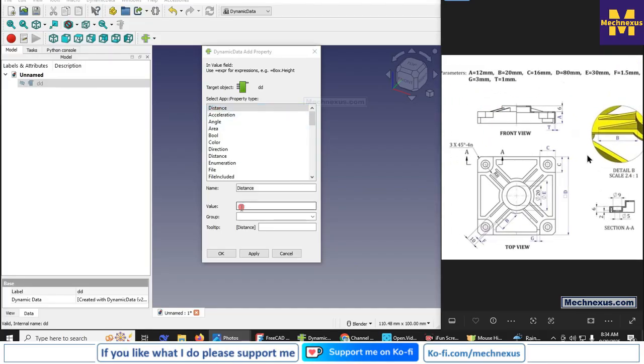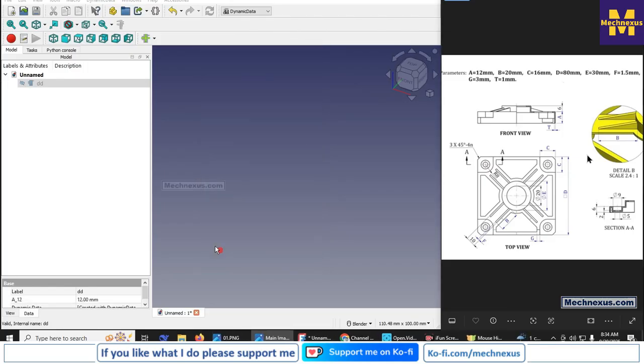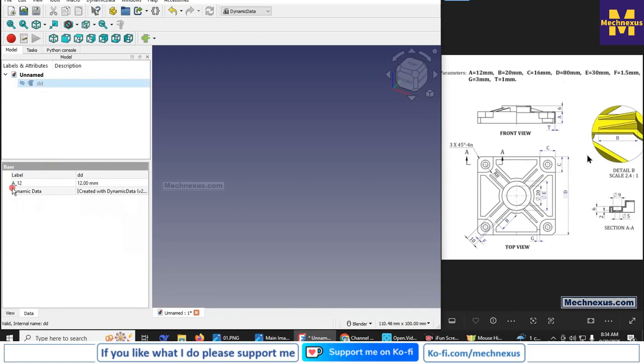First is a distance, and value is 12, and for our convenience we will give it A underscore 12. So this is the name A_12 and value is 12 for better identification, and say OK. Once you click on OK and make it larger, you will see that A12, its name, and value 12 is added here.